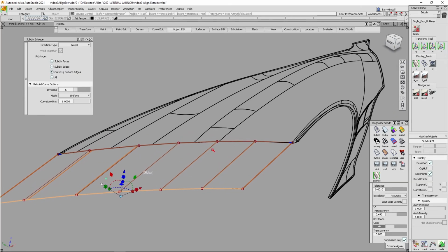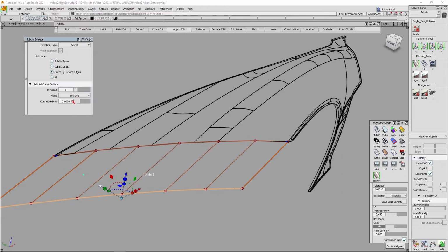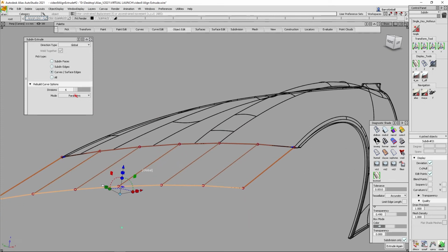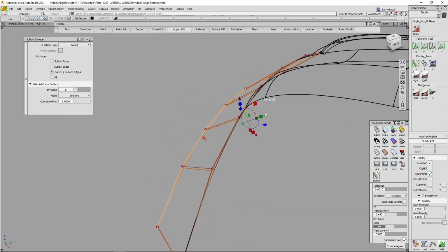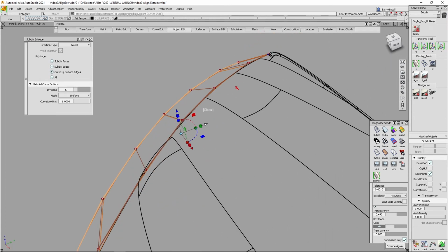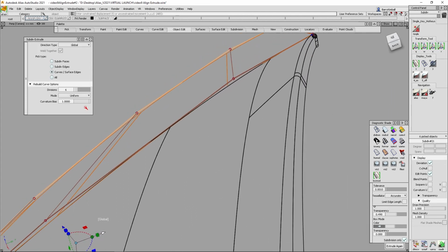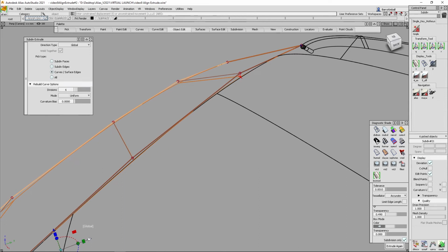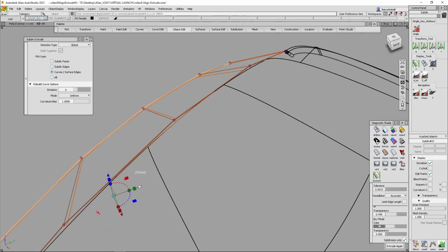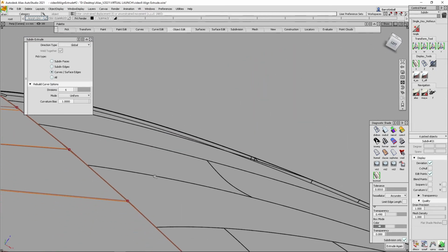or not. And now if we look at some of our options in here, if we use parametric, we can get this solution. And if we use uniform, we get that solution. And if we add in some curvature, we get this solution. All fairly similar, but you do get still the chance to customize those, tune it in till it gets to be looking how you want it. Now see, if I go this way, I can see a little more deviation. I'm a little under here and a little over here. As I slide this into curvature bias, I'm getting a little bit better fit, I believe, along that edge specifically, okay?